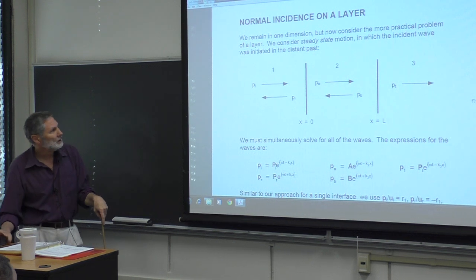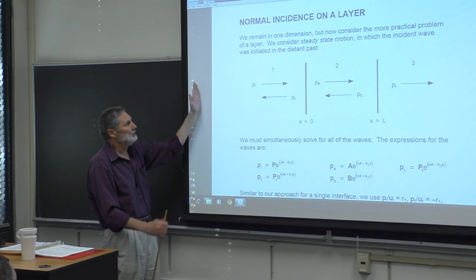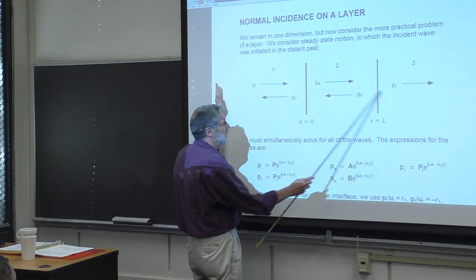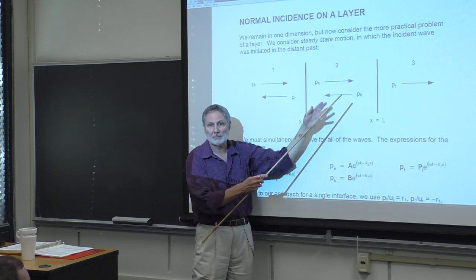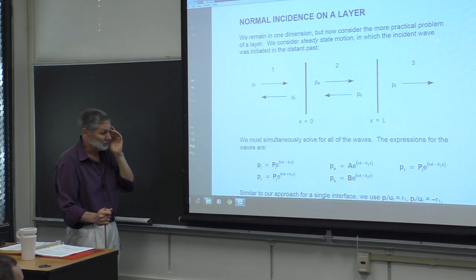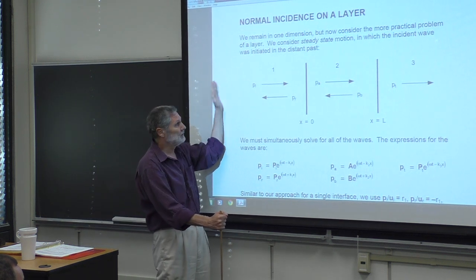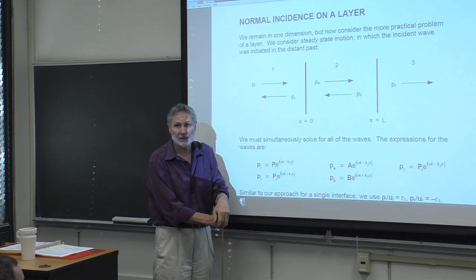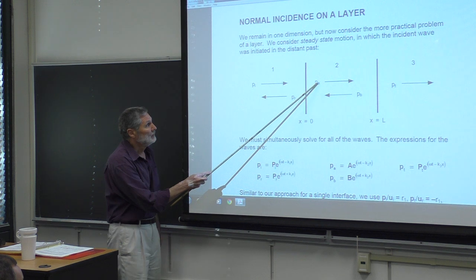So we're going to look at the steady state motion. When you start off with this being quiescent here and you turn on a drive, there'll be transient motion, transient acoustic pressure and particle velocity. Eventually, for a constant frequency drive, the system will settle down into its nice steady state. There'll be a constant amplitude of the transmitted wave.